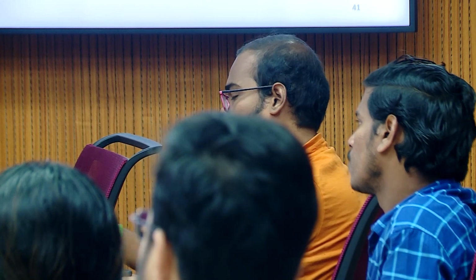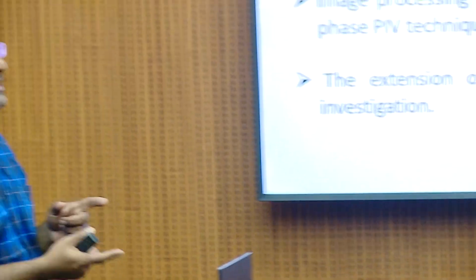The other thing is that I come from the ocean engineering department, so we generally study unsteady flows. When I study regular waves or any sea state interacting with a structure, it won't be a steady problem. There will always be a time-dependent factor, so understanding the stochastic behavior is very difficult. How do we handle the convergence rate in those cases? I assume this is statistically unsteady, but there is some periodicity. Yes, a periodicity will be there.